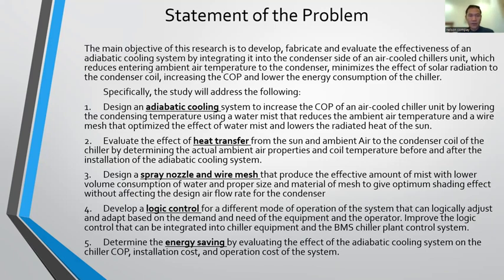Second is to evaluate the effect of heat transfer from the sun and ambient air to the condenser coil of the chiller by determining the actual ambient air properties and coil temperature before and after the installation of the adiabatic cooling system.